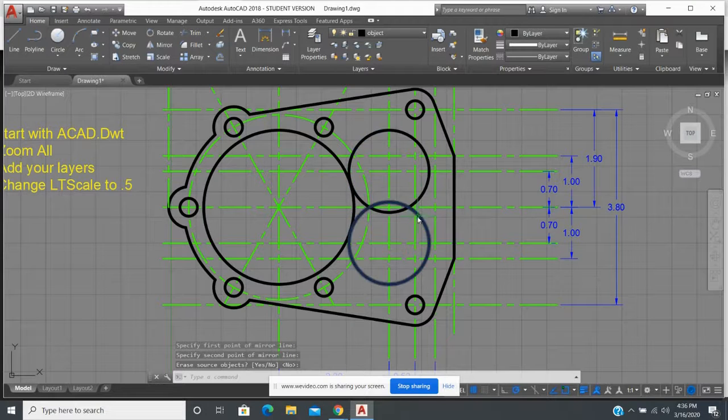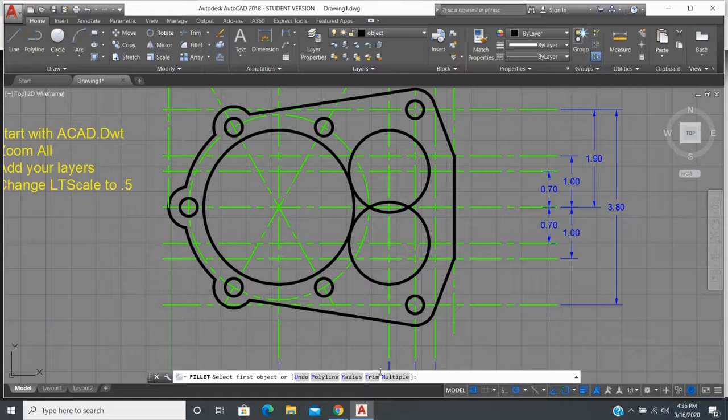And there's actually going to be a fillet in between these two. You could use tan radius, but I'll go to my fillet command. I'll jump down here and click on radius and make sure that I change that to the 0.4. Remember, that was that odd one that we could not necessarily find on our PDF.